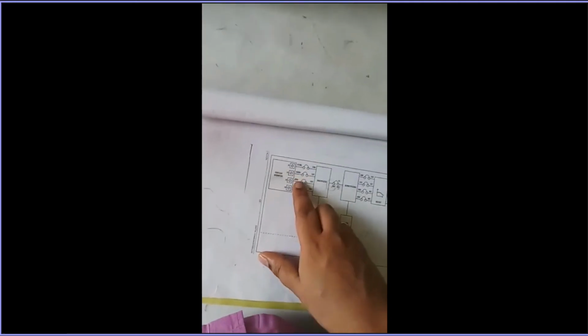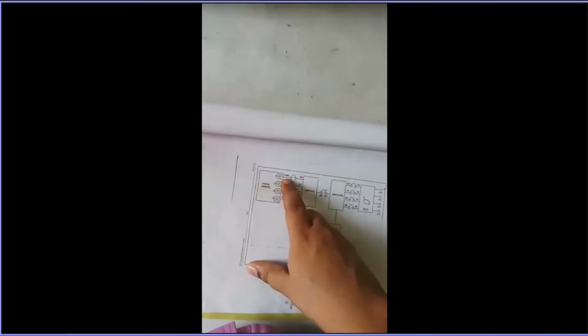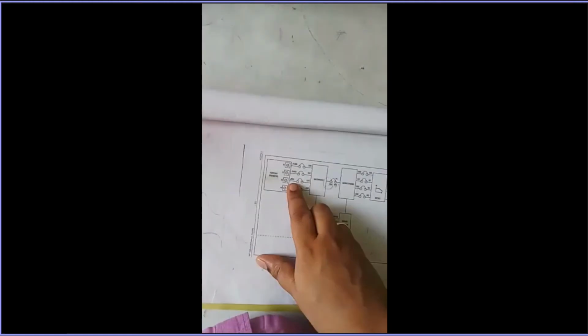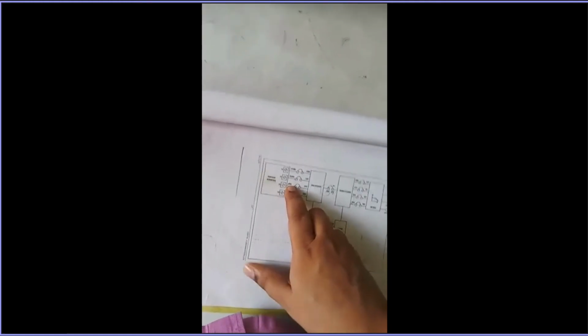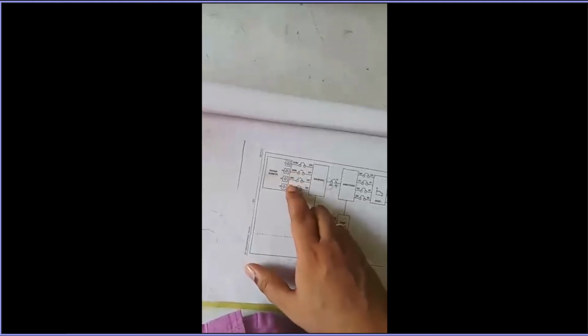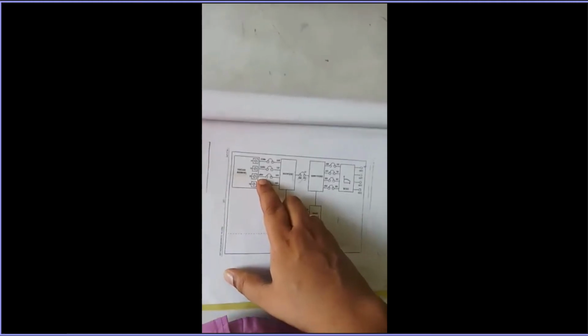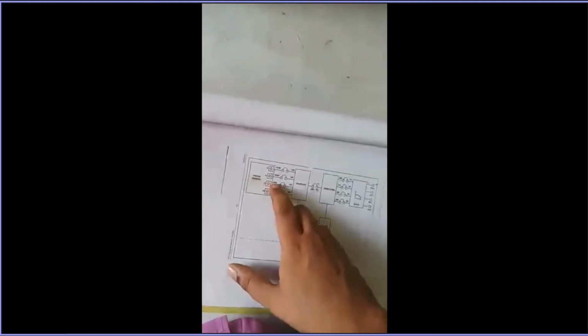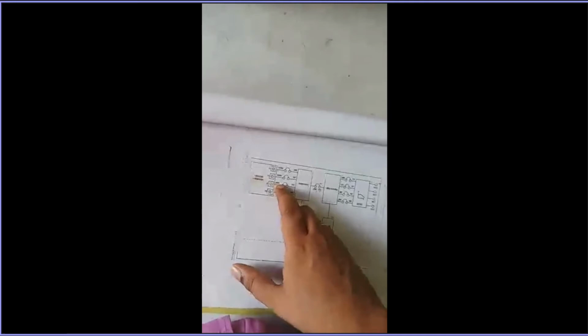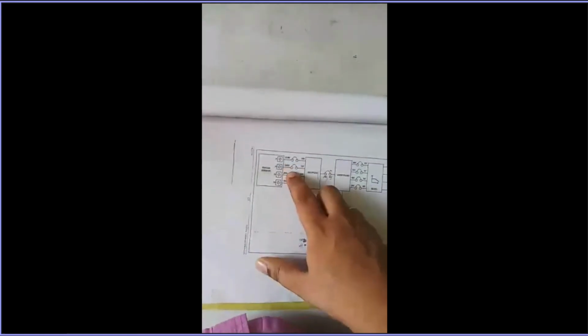If you use a low pass filter or a high pass filter, then if the filter allows 500 Hertz, it will allow 1 kilohertz also. So we should have the band pass filter that will allow only a particular signal band. That means if we have a cutoff frequency, say 500 Hertz to 1 kilohertz, it will allow only this particular portion to pass. That's why we have 4 different filters. Each filter will allow only a particular signal component to pass, 1, 2, 3, 4. And we get the input signal back at this end.